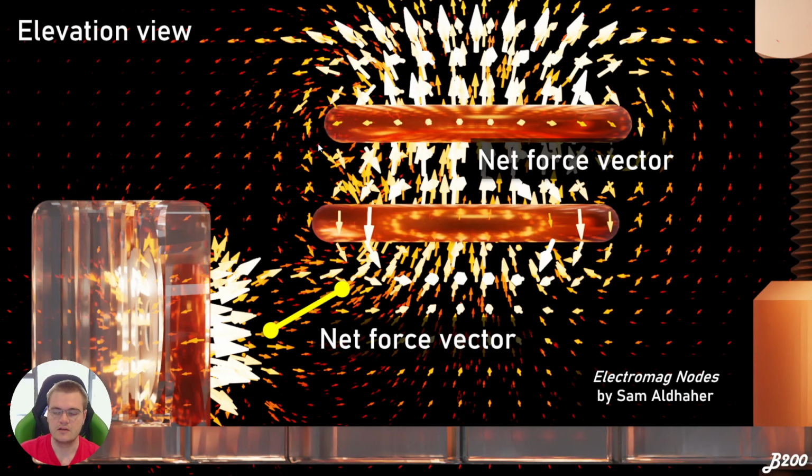And if we look at an elevation view, we can see that the magnetic clutch, if it's positioned slightly below the assembly of the disk, we've got a magnetic field interaction which will result in a net force slightly pulling this clutch in a vertical direction, counteracting the force imparted by gravity, such that the clutch will essentially float right below the disk assembly. And this is to do with the magnetic coupling, and this is also a very stable region, as if the clutch moves down a little bit below, there will be more coupling with the magnetic field, so it'll want to move up back into a stable orientation.